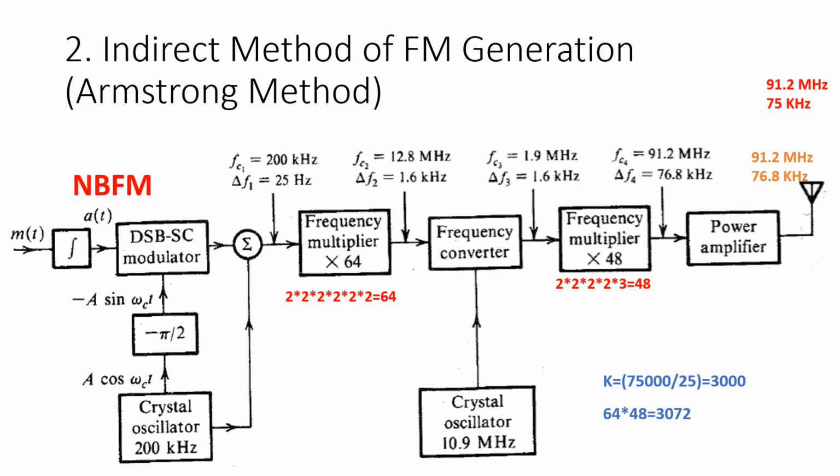So here the number of multipliers, frequency converters and mixing frequency can be designed as per the requirement of carrier frequency and deviation at the output of the FM transmitter.